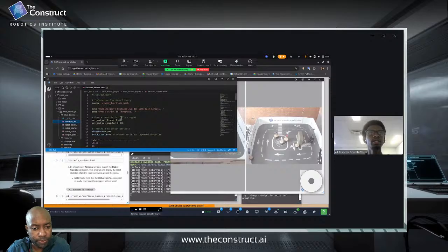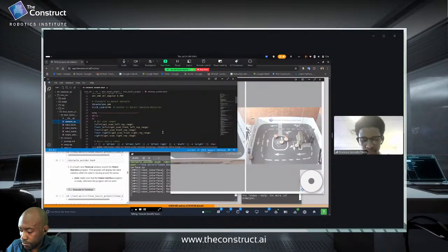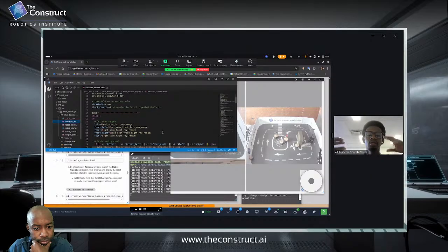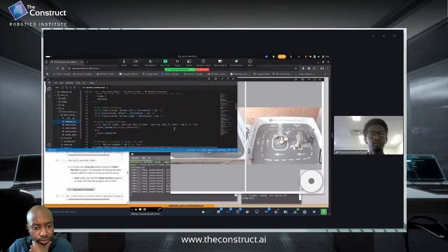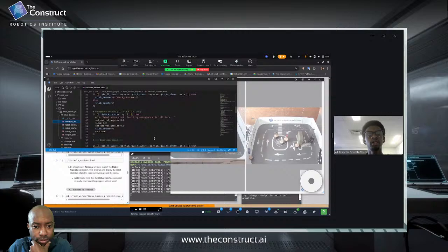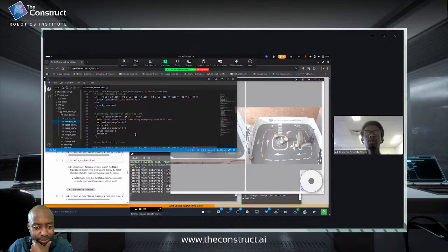So as you can see here, it sets everything to 0, 0 here, and then it sets the threshold, sorry, to 0.300 meters. And after that, based on the scan data, logical conditions decide whether the robot is going to turn left or right, or if it's going to move forward. That's based on the input values it's going to get from the laser scans, the LiDAR scans. And then if the robot stays blocked for too long, there is this emergency recovery portion of the code.